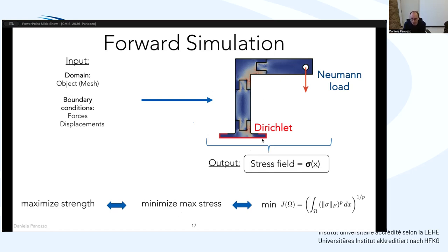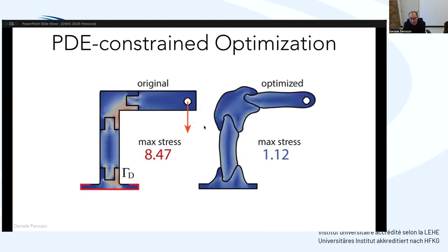You see that these are separate pieces which interact through contact. And if the formulation is differentiable, and everything I'm going to present today is differentiable, it allows you to use shape optimization. So in this case, you get this more organic looking assembly, which has considerably lower stress than what we started from, where unsurprisingly, all the sharp corners disappear and get smoothed out, but in an optimal way.